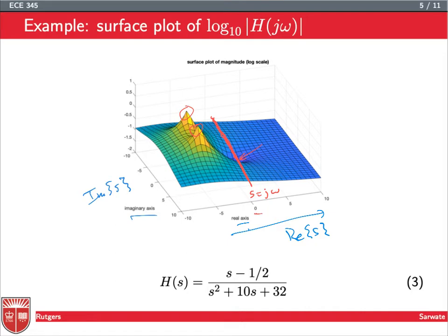And you can see now what I mean by this rubber sheet idea. So we've stuck these 2 poles in there and we've pinned this 0 down. And then you can see you're going to get this little dip in the frequency response, and then it comes back up. And when we plot the frequency, we're plotting it from 0 up, so we're looking at this top part here. So if we look at this, it should start from something low and then pull upward to something slightly flatter. So the question is, okay, now if we use MATLAB to plot the frequency response, what do we get?